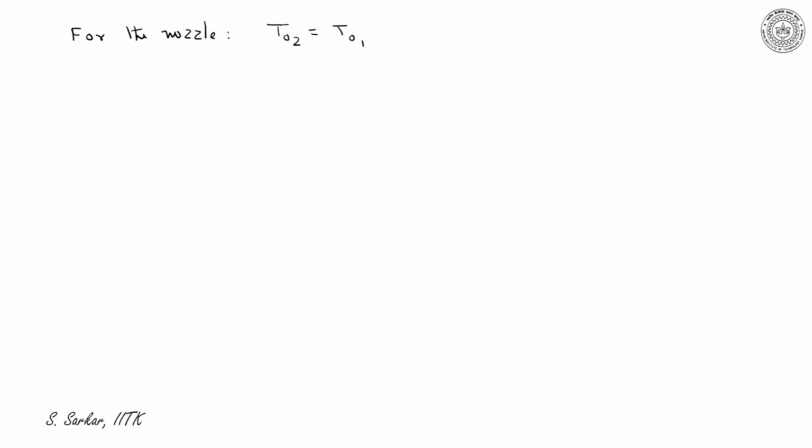That means the total temperature at the exit of the nozzle is equal to that of the inlet. Hence from here I can write T2 is equal to T02 minus C2 square divided by twice Cp.